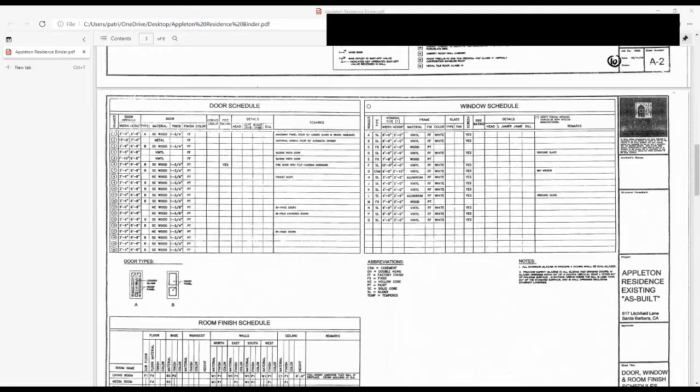Now, in the old days, we used to just make the height 2 inches bigger for a door and the width maybe an inch and a half, 2 inches. So we could tilt it if there was something wrong with the frame, and then we have shims in there. We could go by the nominal size in the old days because they were all fairly close to these.